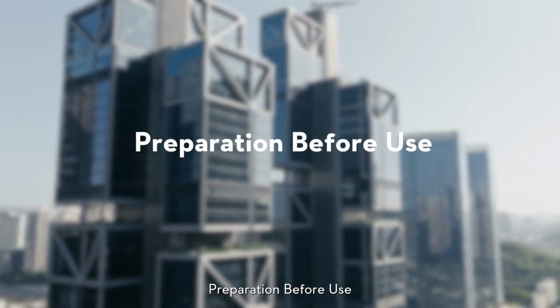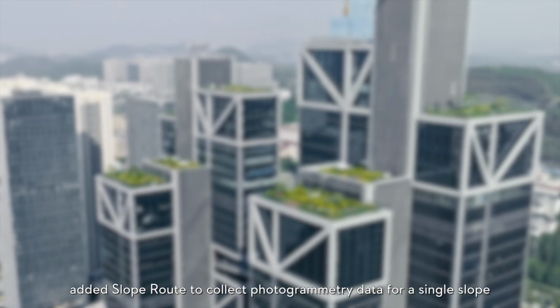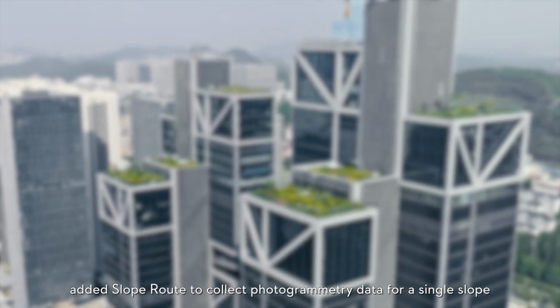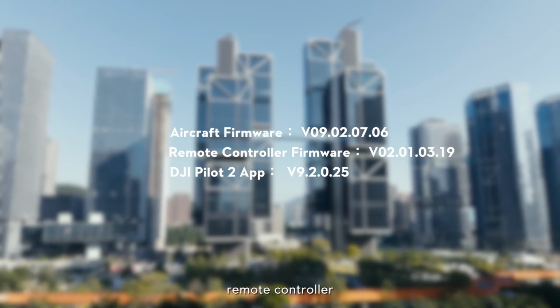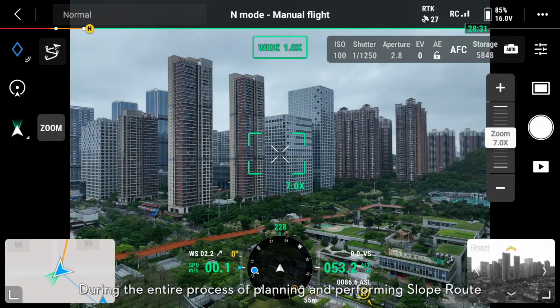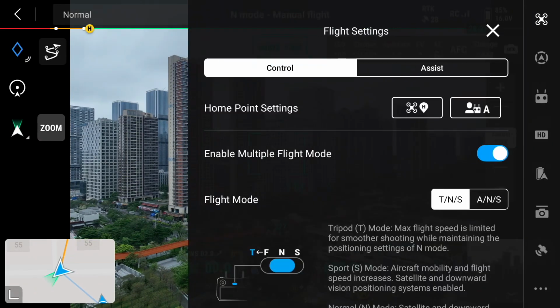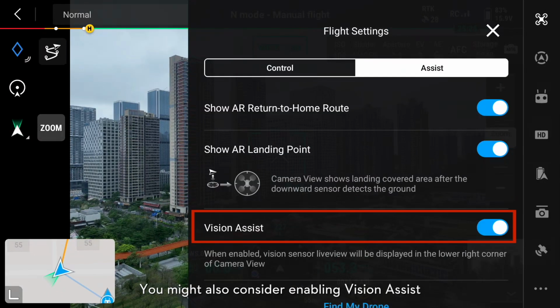Preparation before use. The latest firmware of the DJI Mavic 3 Enterprise series added slope route to collect photogrammetry data for a single slope. Make sure the firmware of the aircraft, remote controller, and app version are higher than the following versions. During the entire process of planning and performing slope route, make sure RTK is connected. Enable Maintain Positioning Accuracy mode. You might also consider enabling Vision Assist to observe obstacles along the flight route and ensure flight safety.